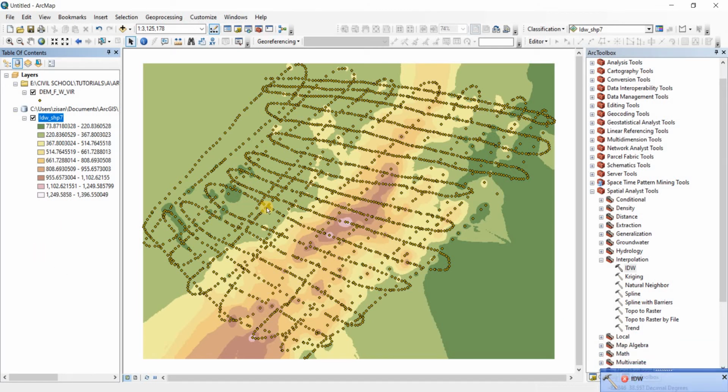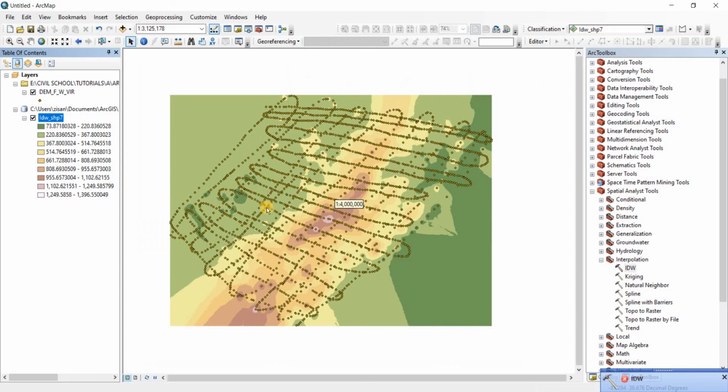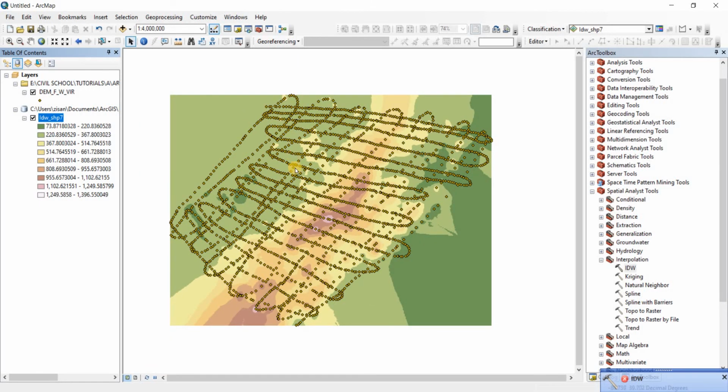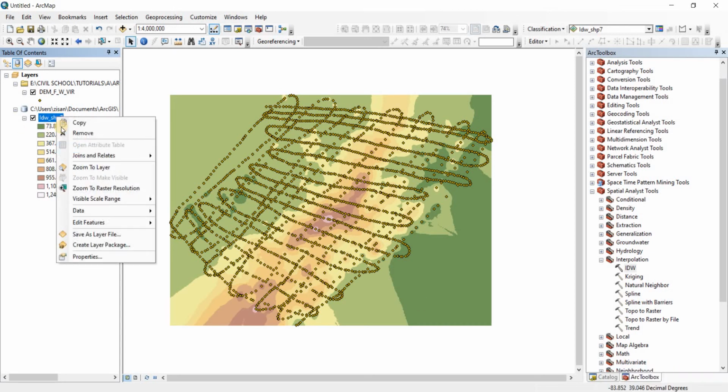So that was it. Alright, so we right now have the raster file for the area we have selected, and you can see the color variations, so it's showing different elevations. Now we have classes. Let's see how many classes we have. 1, 2, 3, 4, 5, 6, 7, 8, 9 classes. So 9 classes is not a round number, so let's turn it into 10 classes.